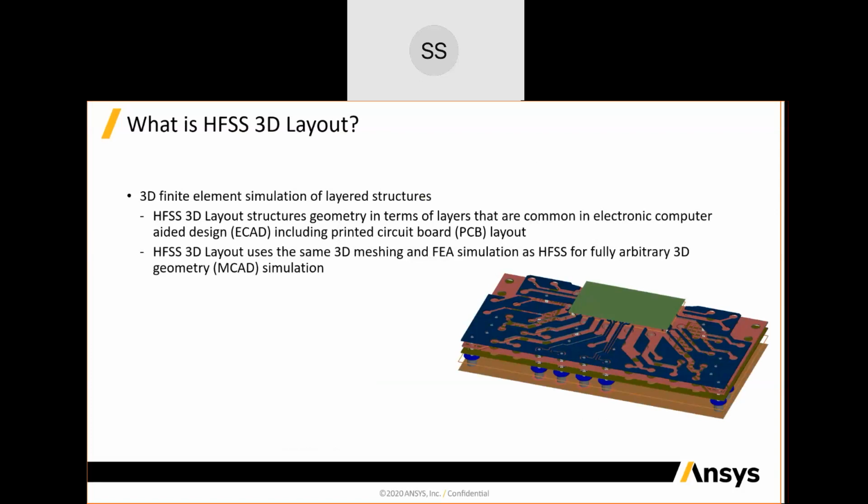And by layered structures, I mean anything that is similar to PCB, so it could be package, or to some certain extent also once we're looking into the chips that might be on a board. But it's everything that's described with certain layered information. And that's really where it differentiates itself from just the common HFSS that we use for other applications, which uses the more traditional MCAD interface, where we describe objects in terms of boxes, cylinders, and spheres.